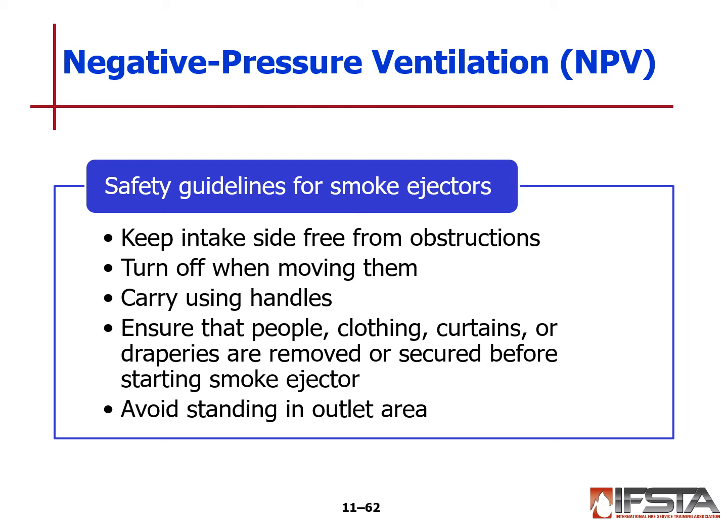Safety guidelines for smoke ejectors. Keep the intake side free of obstructions. Turn off when moving them around, of course. Carry using the handles. Ensure that people, clothing, curtains or draperies are removed or secured before starting the fan, and then avoid standing in the outlet area.